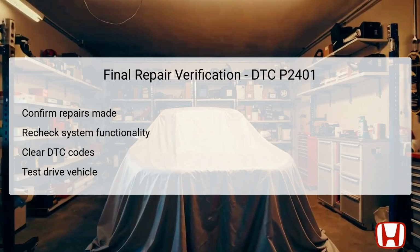After conducting all necessary repairs related to DTC P2401, it is essential to perform final verification to ensure that the issues have been resolved. This involves confirming that the repairs made align with the original problems identified during the troubleshooting process. Once this is established, technicians should recheck the entire system functionality, particularly focusing on the EVAP leak check module circuit and the signals from the PCM.